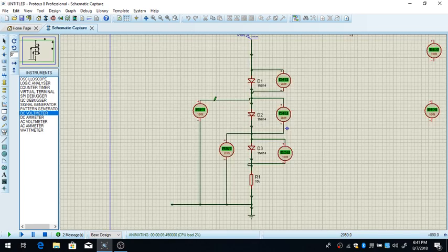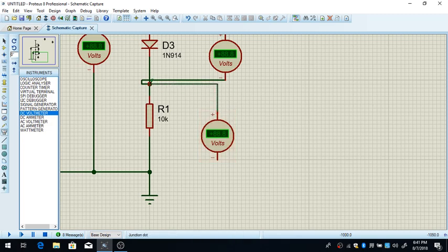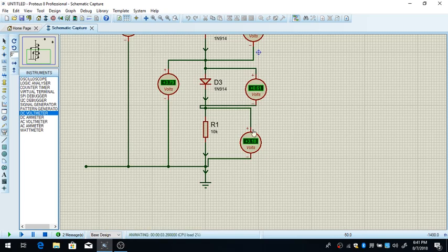Now you can connect a resistor here or a lamp. Now I'm going to connect a lamp, and you will see that here you have a brighter lamp than here. One second. Now here you have 4.4 volts output. Here you have 3.8 volts output, and here you would have 3.18 volts.